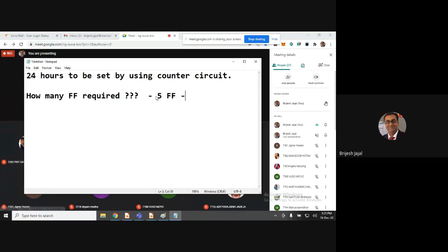If you say 5 flip-flops, the answer is 2 raised to 5. 2 raised to 5 is how much? 32. Right? So fair enough. It means I can set up to 32 hours. No problem. So 5 is fair enough. What about 4? We cannot have 4.5 here, because there is nothing like a point.